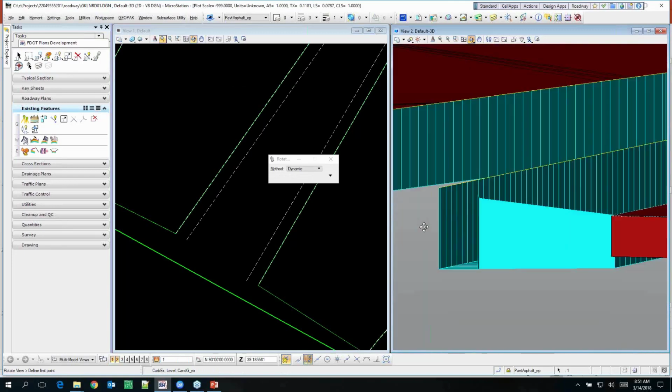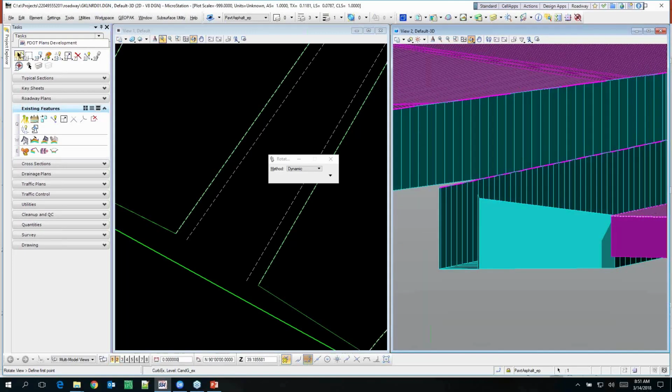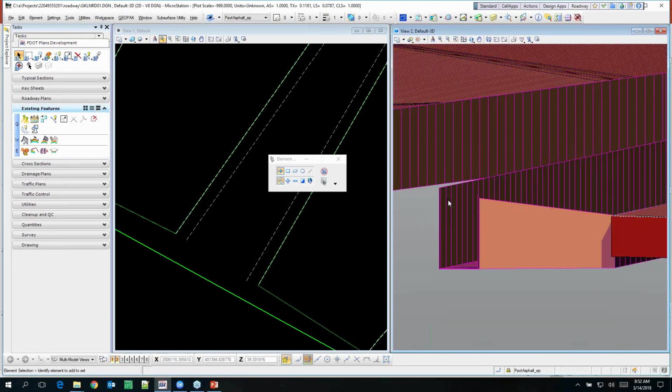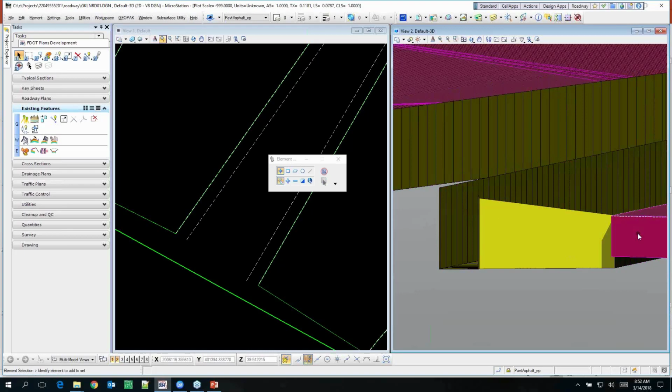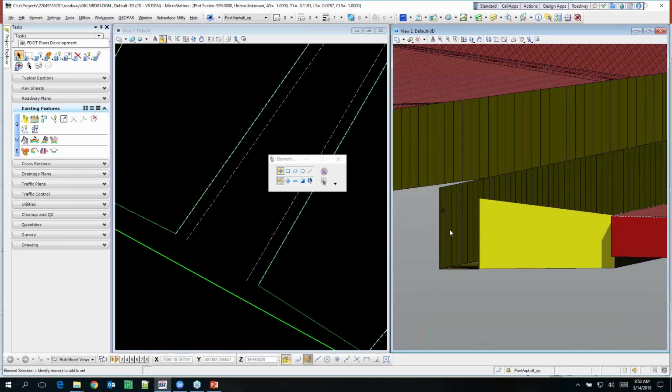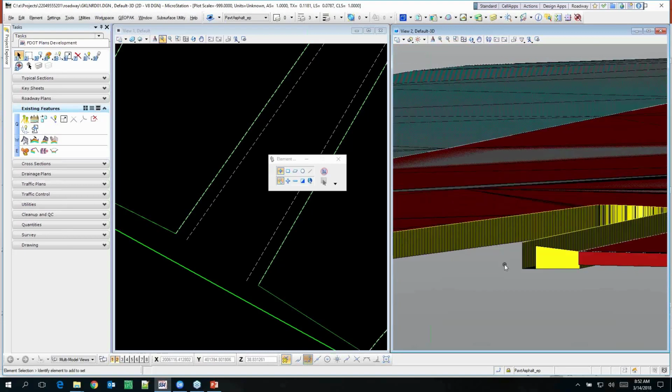Like with turnouts where you have 4-inch concrete with sidewalk, your sidewalk can be 4-inch all the way through. Yeah, sidewalk is the same way as we did with the existing pavement shapes. But you can see the curb is done here, and the height's different here versus here. This just does a cutout in the 3D model, but that way it'll show correctly in the cross sections.